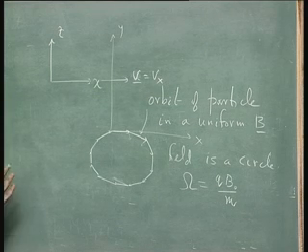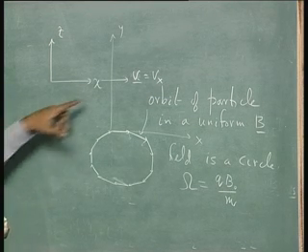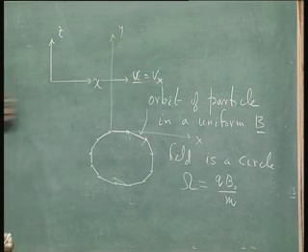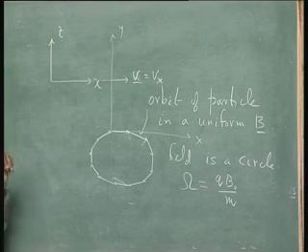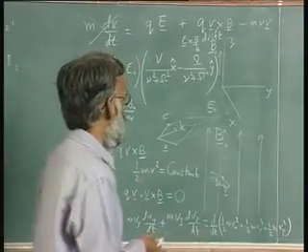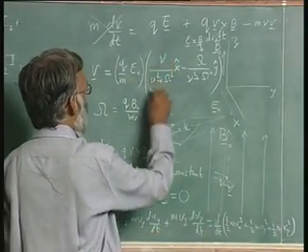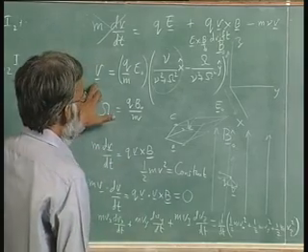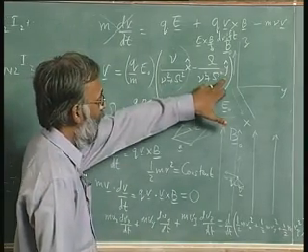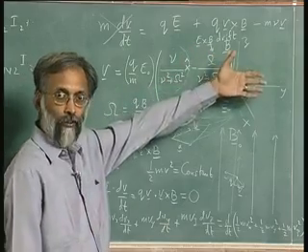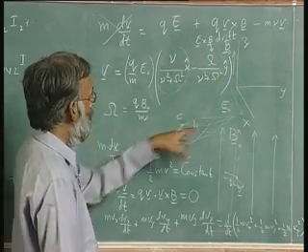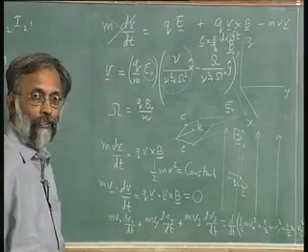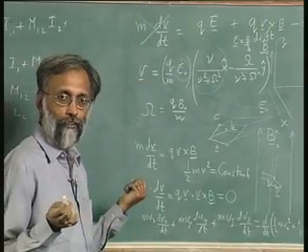Supposing I have a strong magnetic field and I force a charged fluid in the x direction. What these equations actually tell me is, this term is small, this term is large. So I am forcing fluid along a direction, automatically an electric field will be developed in a 90-degree direction.